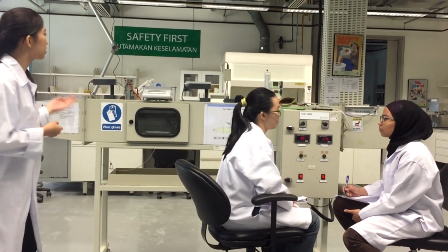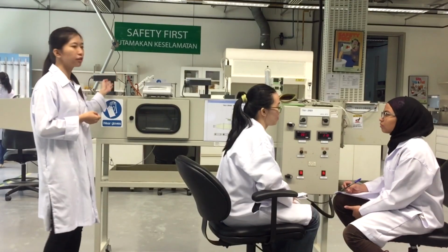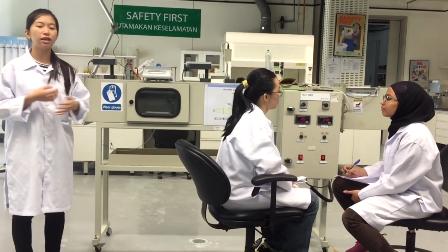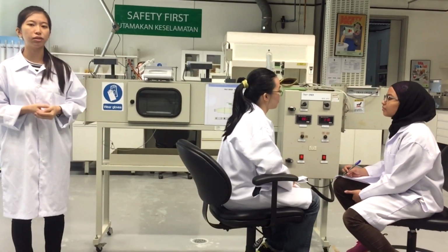While conducting the experiment, we encountered a few errors which affected our result. Some modification and precautions should be made on the experiment so that a more accurate result can be obtained. So the first error is the systematic error of our tray dryer. This occurred in our electronic sensors and also digital balance, which were not calibrated properly to fit our experiment. To overcome this, proper checking and calibration should be made on the equipment of the tray dryer so that they can function at an optimum level.